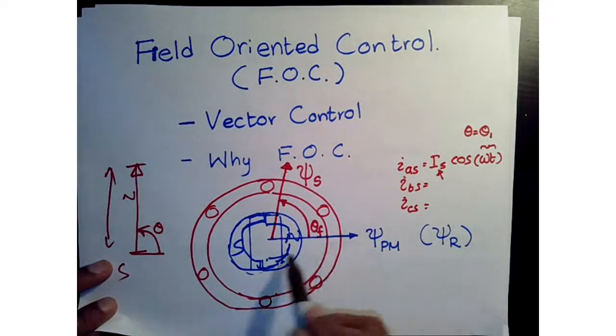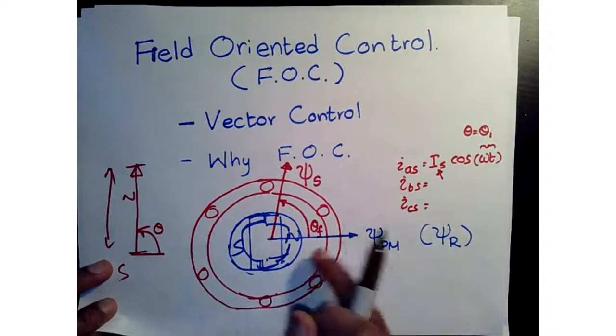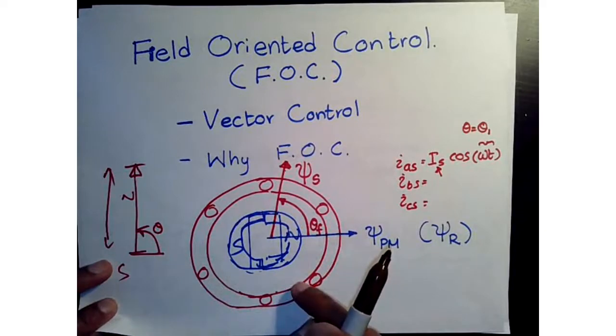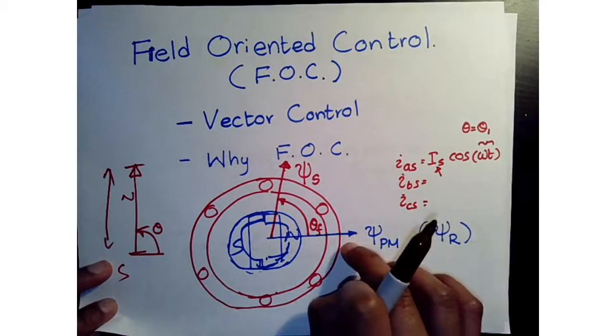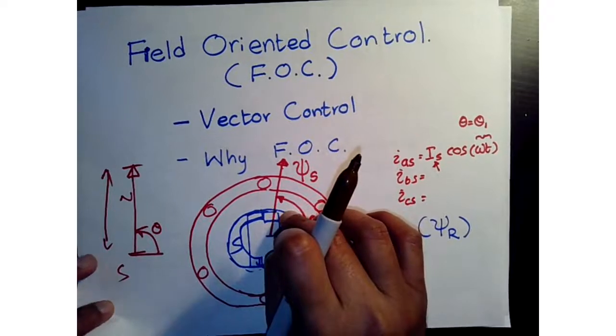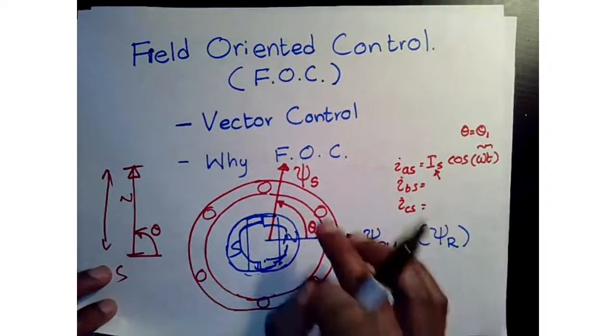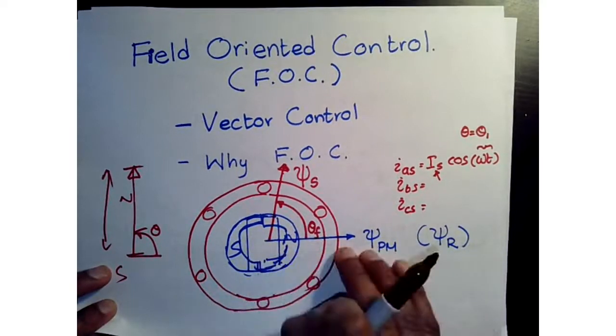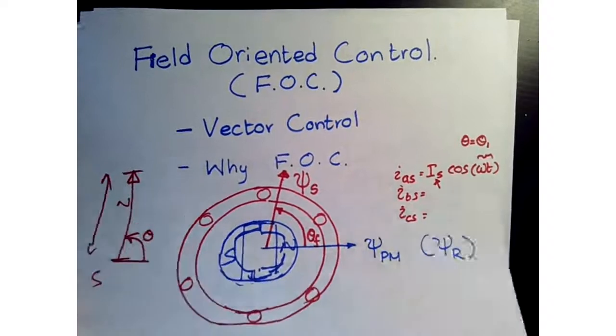When the machine is rotating, it could be at any arbitrary position, and unless we know where it is, we cannot optimally place our stator flux vector. The way to measure how the permanent magnet flux vector is oriented is to use a position sensor.